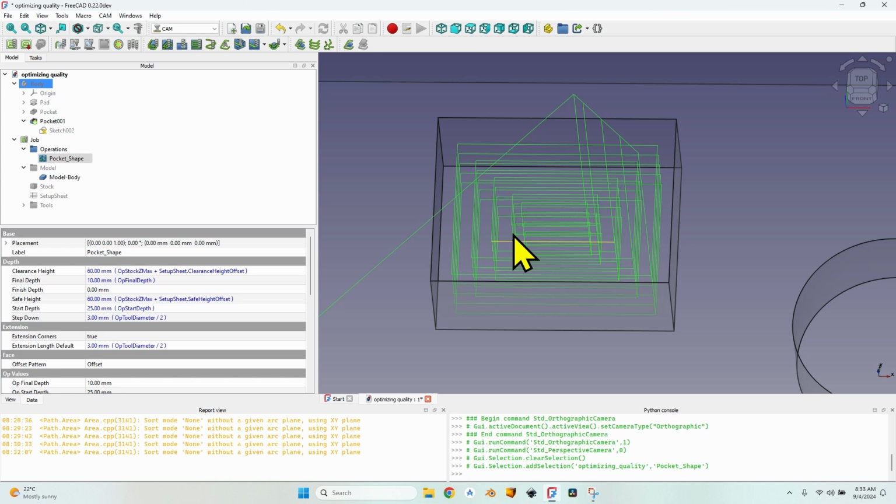is composed of two parts, because whenever you're milling a pocket you have to remove a lot of material. So mostly the parameters for removing the material will be pretty high. Toolpaths with a big distance between them, a step down as big as possible because you want to do things fast of course. But after milling most of the material you want to get a smooth finish.